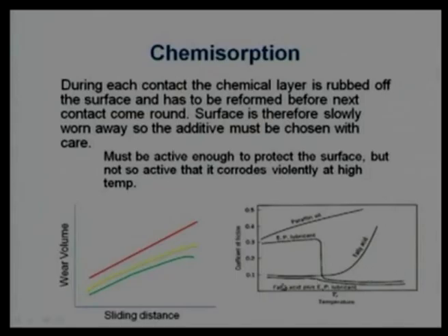So overall, if I want to make a good lubricant package, I will be using mineral oil or carrier fluid with fatty acid plus EP additives. So the overall package gives us a satisfactory performance. It gives a low coefficient of friction compared to pure base oil, compared to EP additives and base oil, compared to fatty acid and base oil. The overall package needs to have all together.